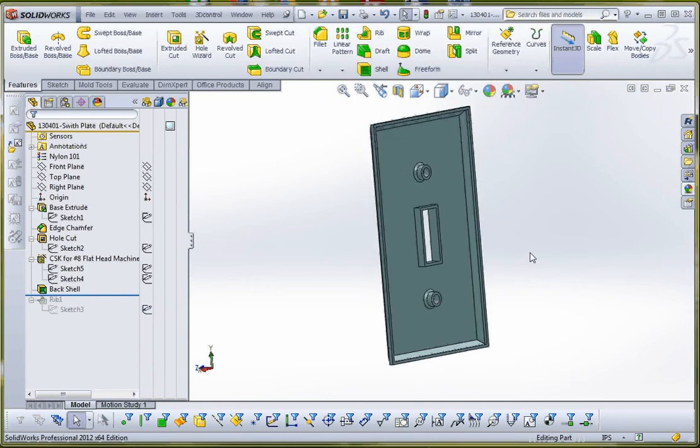Again, we'd probably have to take a switch plate apart and maybe look at that a little bit closer and see what the actual thickness of that might be. I don't think there's any real standard for that. It's probably driven by the plastic involved and how quickly they want to be able to mold this. And you're probably going to find a whole bunch of different standards out there. But this looks reasonable. Again, this is just a reasonable model, strictly designed to get you started in SolidWorks and show you some good basic sketch geometry that's going to help define this whole model.